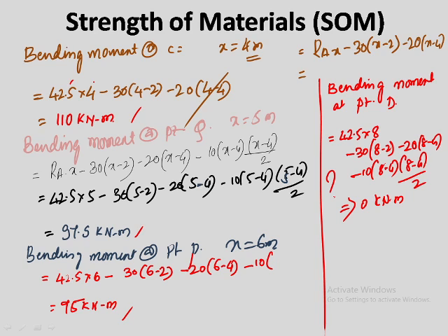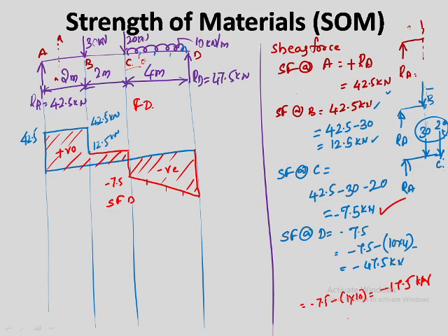Yes, sir. You got a 0? Yes, sir. Then solution is 100% correct. You go for cross checking somewhere, either for shear force or for bending moment. You should get a bending moment at supports 0 here. At supports BM should be 0. Then solution is right, otherwise wrong.